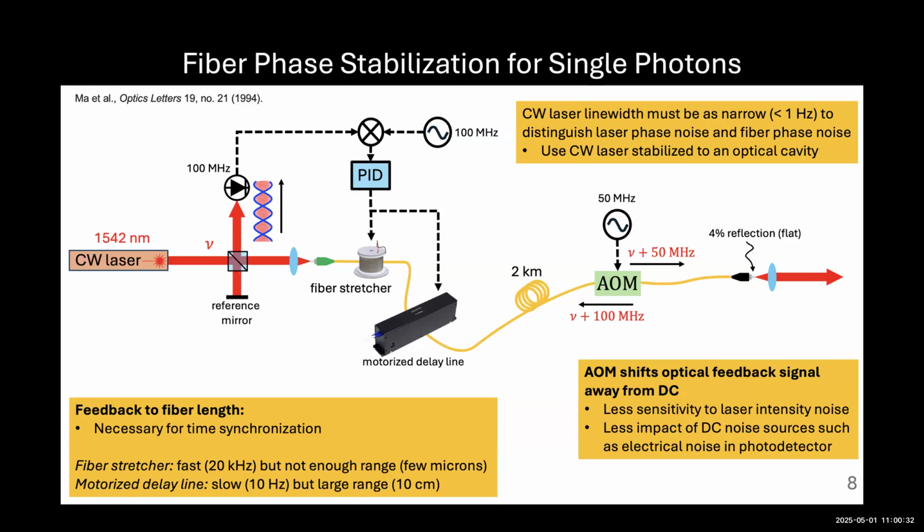But then you want to send light with much higher frequency information, at 50 gigahertz or 100 gigahertz or something, maybe doing phase measurements of that. Are you saying that when you correct for the low frequency noise here, the high frequencies you don't have to correct for because they're so small? There is a bandwidth to all of these feedback actuators, but what we're really tailoring that bandwidth to is how much noise is inherent in the fiber.